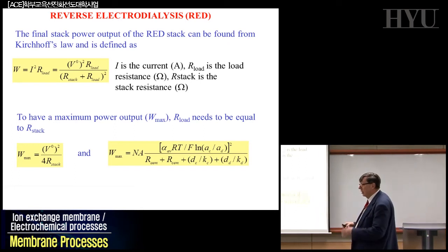And that is very much related to the flow dynamics, nothing to do with the membrane itself, but with how you realize your system. This is the equation you can utilize in this condition to calculate the maximum voltage and the maximum power, the power density I mentioned before, which you can see depends on the resistance of each one of the membranes, the conductivity of all the boundary layers, the size of the boundary layer, etc. Again, these have nothing to do with the membrane itself, but with the engineering of the system, and that's why you have to realize this kind of condition at its best.